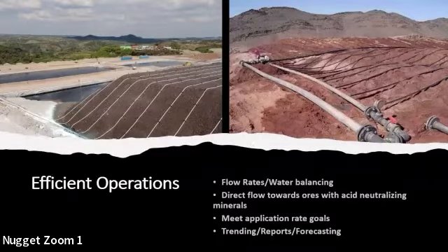All right, I had mentioned the correlation analysis. Something else that we did is that we have the hydraulic conductivity measurements we performed, and we wanted to look at correlating those to fairly easy to measure, low cost physical measurements. So we looked at the PSD indicator, which I presented before, but just as a reminder, it's percent greater than 4.75 millimeters, so percent gravel, divided by the percent passing number 100 mesh.